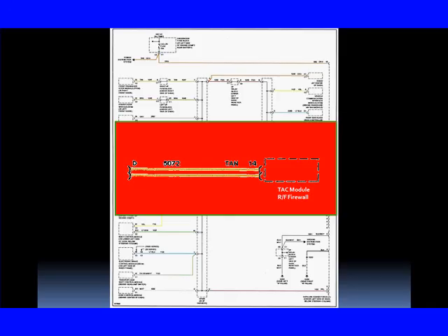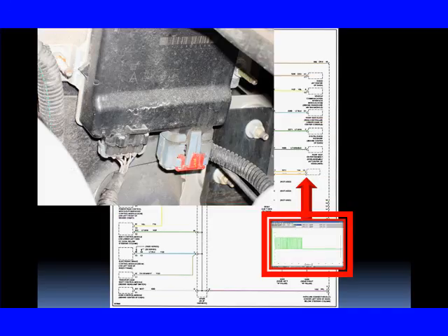It's got two wires. Now, that's not the only two wires going to that module. Those are the two wires carrying communications to that module. It has two wires for communications, redundant communication lines. It doesn't need but one, but it has two because of redundant systems. Here it is on the actual vehicle, on the fender well over here. And there's the signal we'll be using.